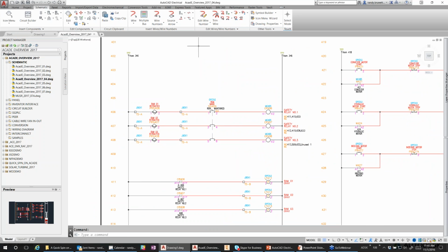Using AutoCAD, I would start the line command, use object snaps, and so on. With Electrical, it's as easy as picking my Add Rung command and picking approximately where I want the rungs, and Electrical takes over and adds the rungs, adds connecting dots, and so on for me automatically with just two clicks. It even knows, because I have the rung referencing system used on the side here, where those lines should be located. The ladder system you see here is just one style of system. AutoCAD Electrical can also manage point-to-point style systems, wiring diagrams, connectivity diagrams, one-line, three-line, and so on.